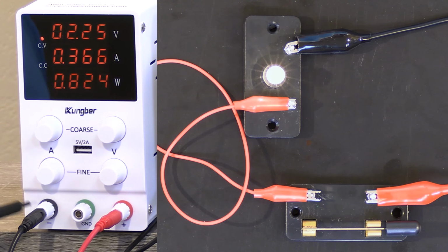In a circuit, the reference point for this voltage on this readout is between these two terminals. So it's telling me there's 2.25 volts, which, we'll talk about units in a minute. Volts is the units of push in a circuit, right? But it's the units of push that exist between these two wires. It's always between 2 points. Voltage is always between 2 points. You cannot measure voltage at a single point.